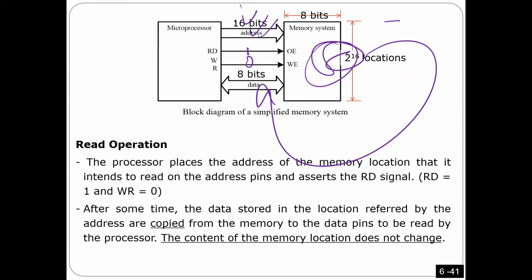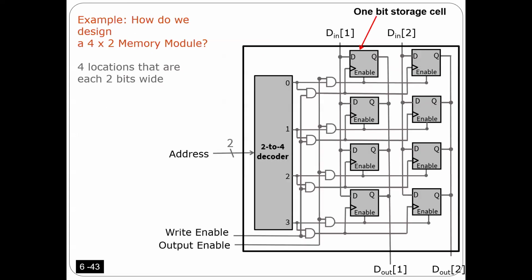How the hardware, once you put an address and you put 1 here, will get whatever value is there and give it to you at the output here. A very high level description. So for example, if you have a memory like this one, you have the address here. This is a very small memory. I'm assuming in this memory we have 2-bit addresses, only 2 bits. Okay, and that means we have four locations. So this is 1 location, 1 location, 1 location, 1 location.